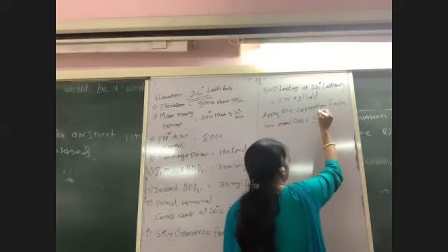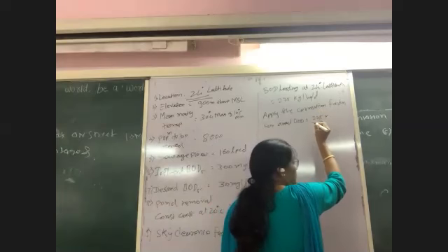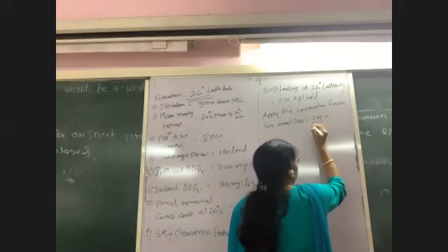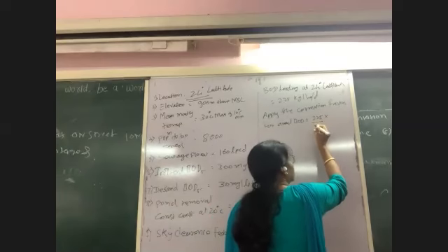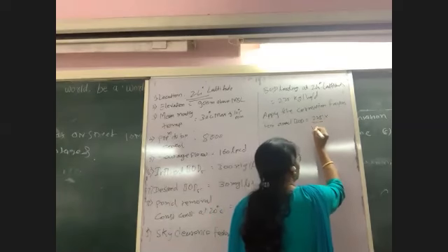How to apply the correction factors? The sky clearance should be multiplied and the elevation factor should be in the denominator. Multiplied by 0.9. So you will get the applied correction factor for BOD.